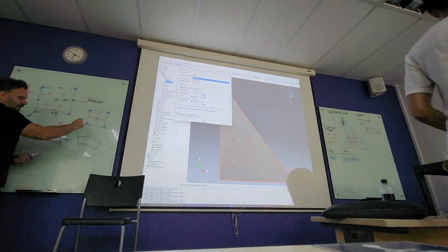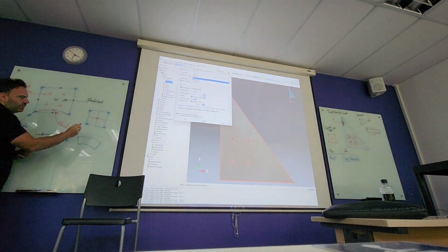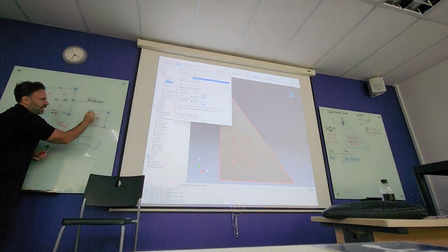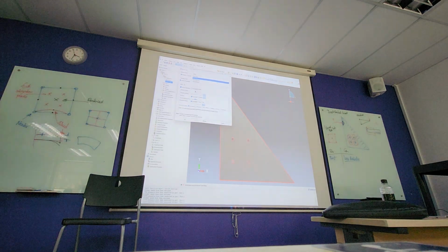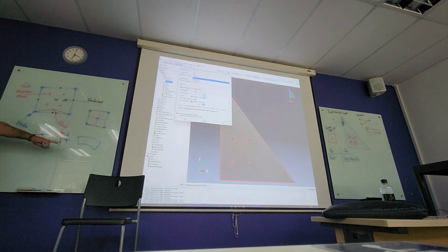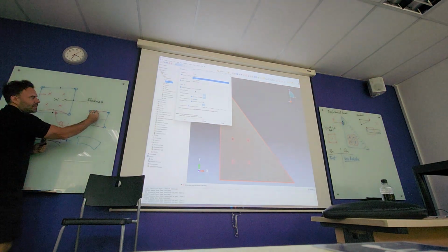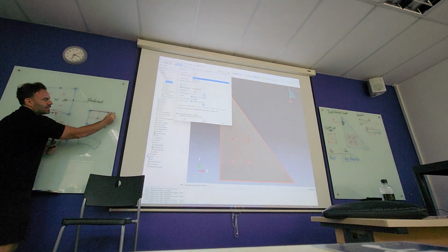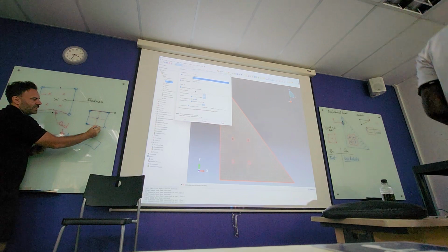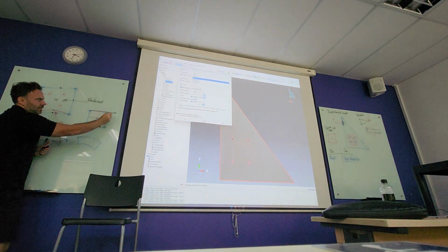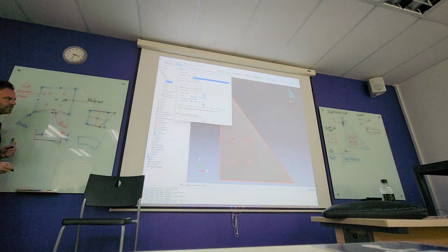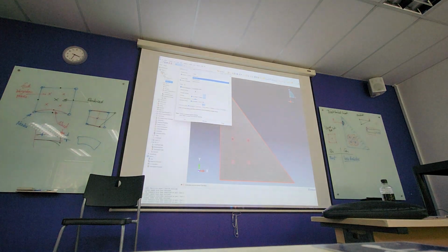So this one here, this edge, both of these edges, that edge and that edge, it cannot curve. Yeah? So if you want to capture a situation like this, what you will observe is that this side just gets a little bit longer and this side gets a little bit shorter. Yeah? That's basically what happens.